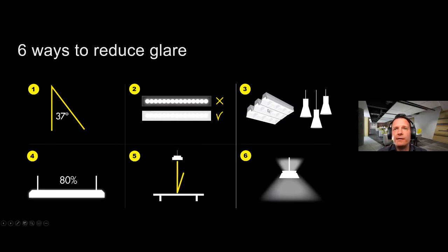Then, of course, you can shade your luminaire, or have some kind of shielding around your luminaire. You can also reduce the lumen output, but of course that might require adding more luminaires to achieve the required lux levels in the area. Then, the placement of the luminaire relative to your task should avoid glare on the task area. Maybe also increase ambient light. And finally, use more indirect light as well, so that the contrast of just your luminaire is not so strong.